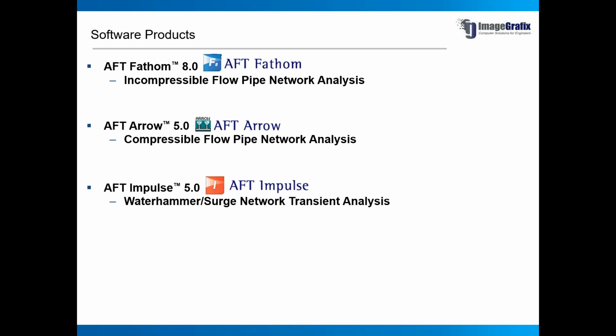with AFT Arrow. Then the third one is AFT Impulse, which is typically for water hammer and surge analysis. Pump trips, valve closures, pump startup, shutdown situations, etc. are modeled with AFT Impulse for water hammer and surge analysis. And then we can also do the modeling with surge protection devices like surge tanks, liquid accumulators, air release valves, vacuum breaker valves, to name a few.